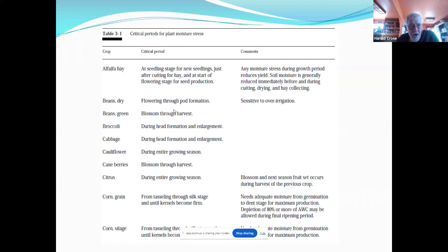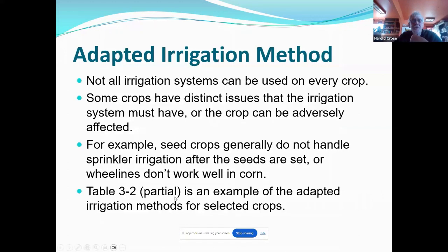I'm behind. Even though I fill the profile, you're just not going to catch up with the system you've designed to apply water every 3 days to that crop. So it's very important to understand the agronomy behind the crops you're planting in some of those critical stages.